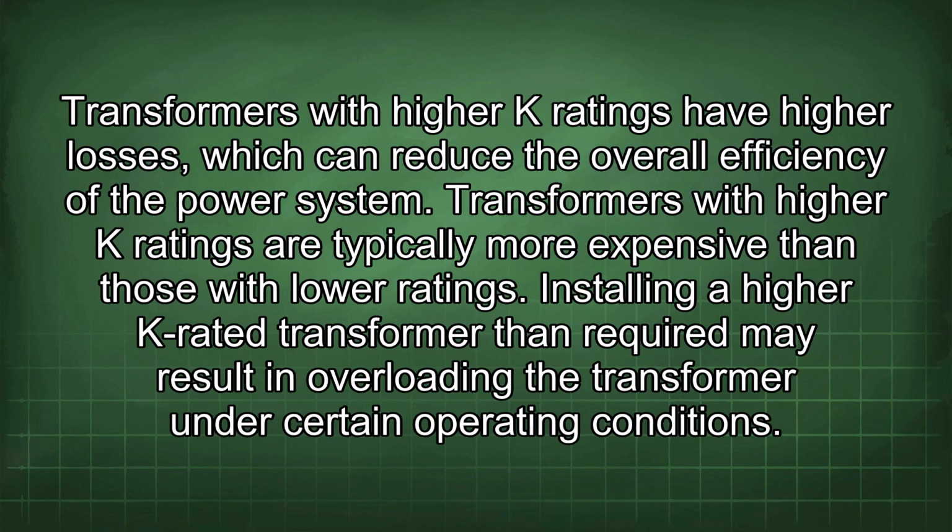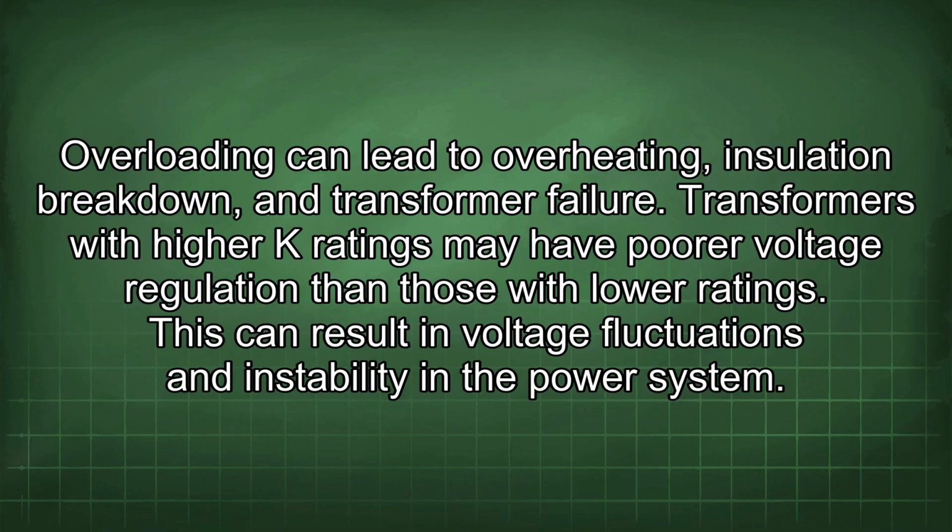Transformers with higher K ratings have higher losses, which can reduce the overall efficiency of the power system. They are typically more expensive than those with lower ratings. Installing a higher K-rated transformer than required may result in overloading the transformer under certain operating conditions. Overloading can lead to overheating, insulation breakdown, and transformer failure.